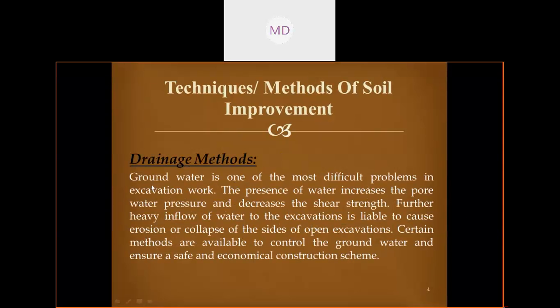Groundwater is one of the most difficult problems in excavation work. The presence of water increases the pore water pressure and decreases shear strength. This is natural, you know this thing. If pore water pressure is increased, then the shear strength will obviously decrease.